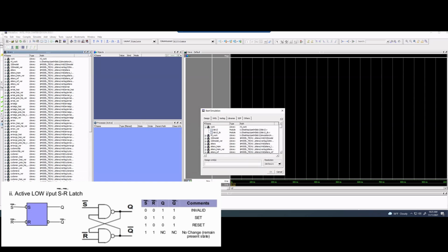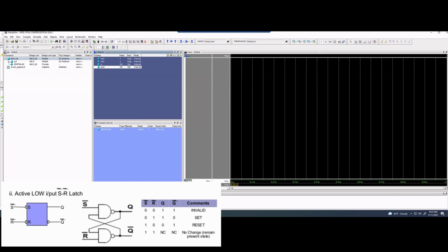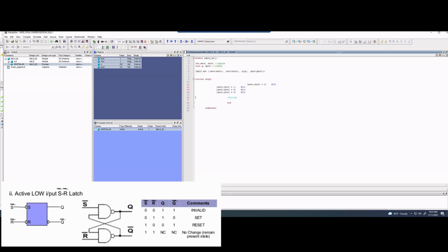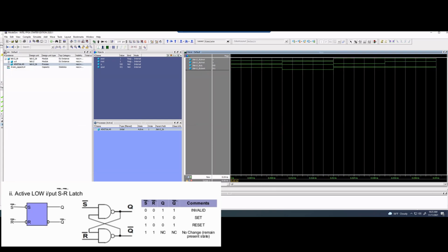We want to expand our work. Click Test Bench, click OK. 0 errors, 0 warnings. So this is what it's going to look like. Now we can Control-click all these and bring them into here. We'll click Run again right next to 100 ps at the top. We don't want to finish, so we'll click No. And then we can go back in here, and we're going to right-click and then zoom full.